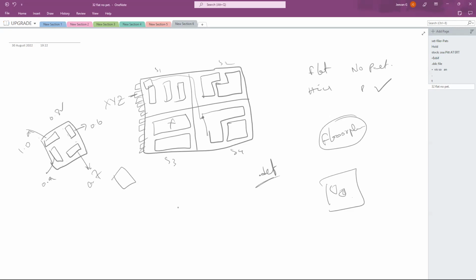In this area the cells will be working at 1 volt, for example, in this area 0.9, etc. So these are separate voltage areas, meaning the cells in each particular area will be working at a different voltage. The information related to these voltage areas you can see in the UPF.